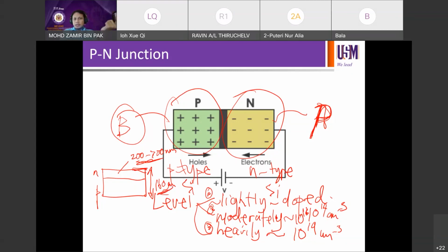In a silicon solar cell, for example, typically the optimum doping level would be 1.5E16 for the P-type wafer. And then typically for the emitter layer, we normally use around 2E19, for it to perform the best, for the conversion efficiency to be as high as possible. Because there will be effects of different doping levels.